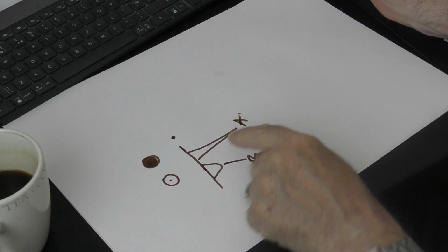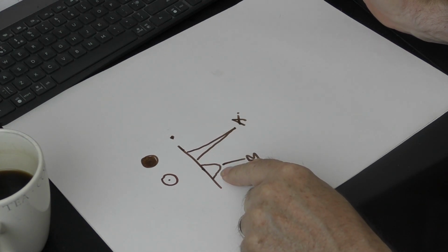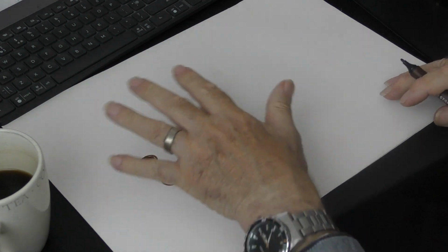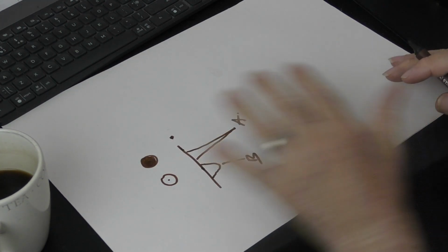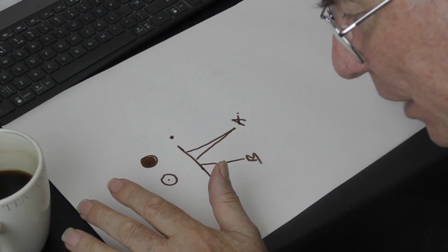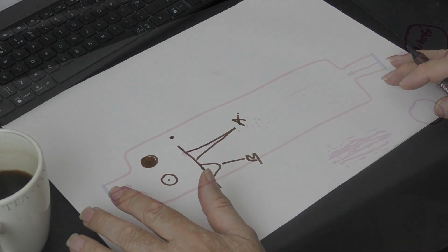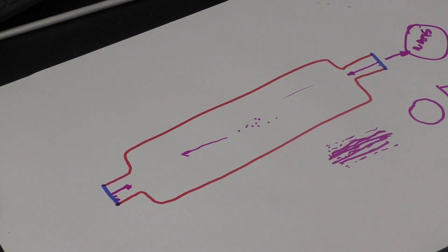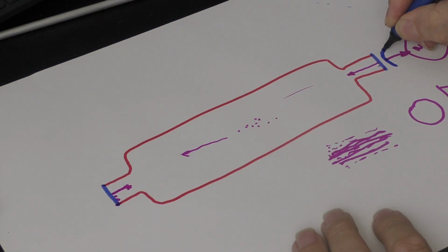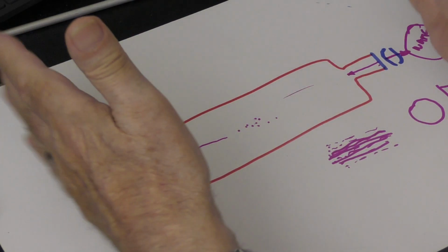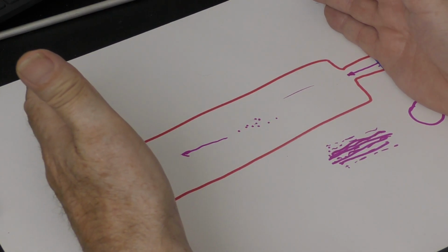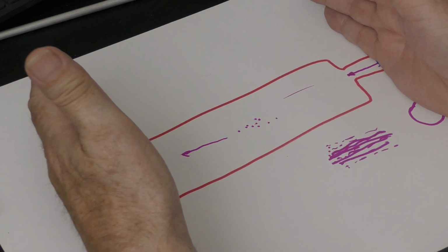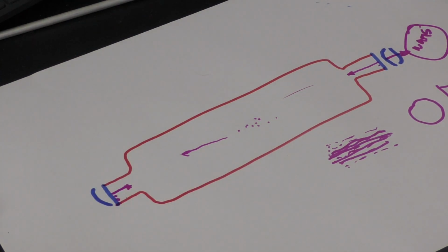This is good at cutting. This will be okay for engraving, but pretty inefficient at cutting. But that's not what we're about today. What we're trying to find out is why temperature is affecting our power output. You can create a B-grade tube by distorting these mirrors. You can't change the parallelism. You've got an A-grade tube to start with, which is parallel. You can't make them any less parallel, but what you can do is cause the mirrors to somehow distort.